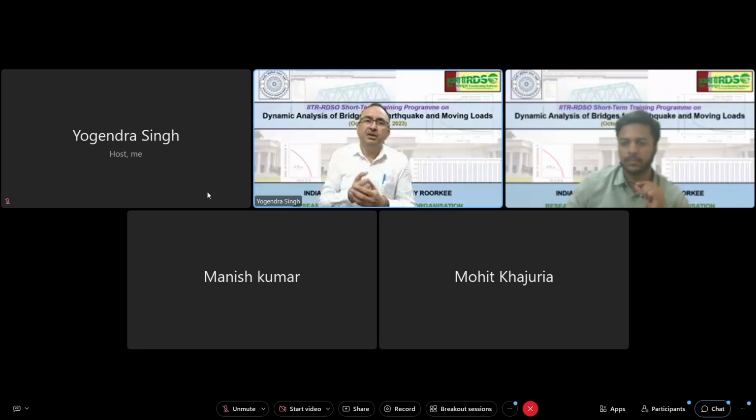So the period we are considering in the probability of exceedance, 50 years, 75 years, or 100 years, whatever period you want to put, that is going to give us a higher target response spectrum. And when we select the ground motions corresponding to higher target response spectrum, we will get higher intensity and probably higher magnitude and closer distance.